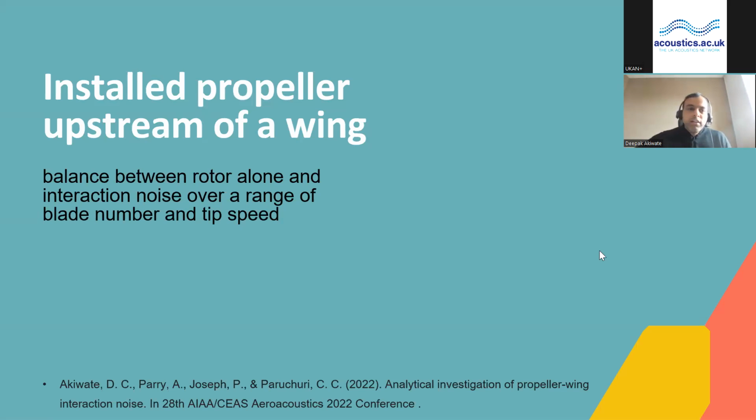So until now, we looked at the uninstalled propeller noise. Now we will look at the installed propeller noise, with the propeller upstream of the wing, and we will look at the balance between the rotor alone and various interaction noise sources over a range of blade numbers and tip speeds. These are results we already published at one of our AIAA conferences in 2022, which was held in Southampton itself.